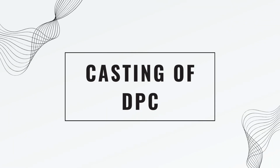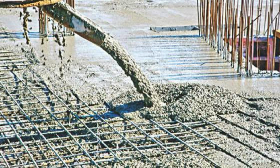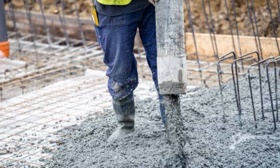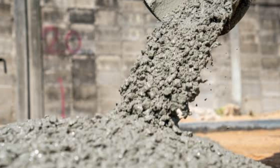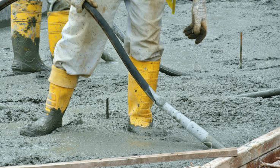Okay. Now, the next stage we are going to be talking about is the casting of the DPC. As I said earlier, the DPC is also known as a damp-proof course. Now, casting of the DPC requires preparation of wood formwork around the edges of the house. Once the formwork is ready, casting of the DPC can be done by pouring the mixed concrete gradually until you arrive at the required thickness. Please ensure that the concrete is properly vibrated and the thickness level is properly followed.